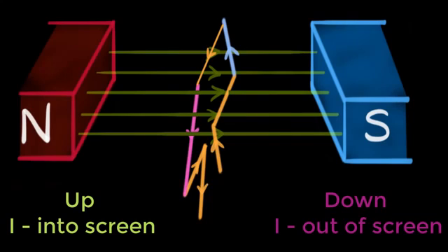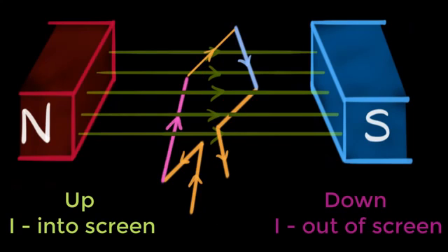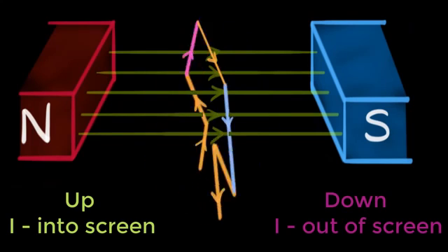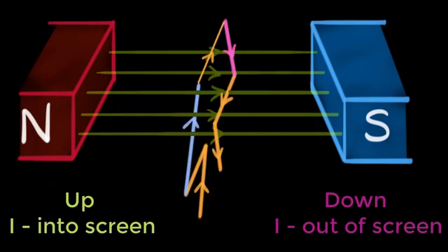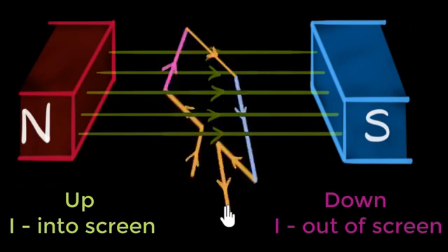the left side. Because now again, the pink wire starts going up, the blue wire starts going down, and as a result, the current in the pink wire will be inwards, the current in the blue wire will now be outwards, the current will again reverse. So every time our coil is in this position, which is perpendicular to the magnetic field, we will see that the current direction will flip. And so if you look at the entire animation now, it looks somewhat like this. Every time the coil comes in this position, perpendicular to the magnetic field, the current direction keeps changing.